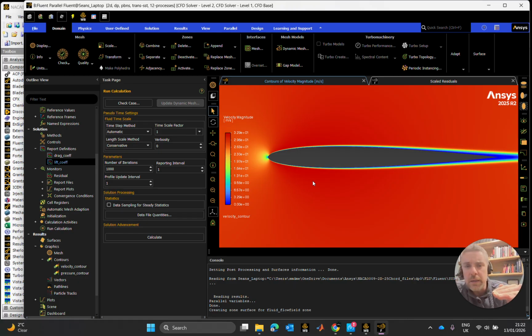It'd be very unlikely that we'll get a full 0 on this, for the simple reason that when we run this in CFD, we'll have inherent errors, whether it be the numerical error itself, errors to do with the discretization, and errors associated with rounding off numbers, kind of our machine error.